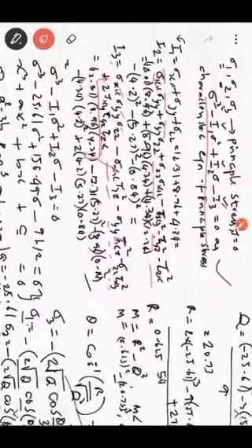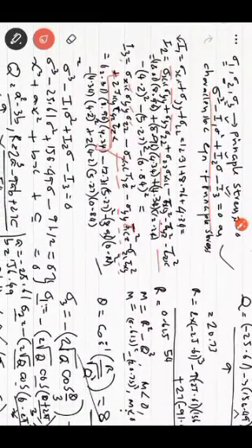And you have to add 2 times tau xy tau yz tau zx. These are all formulas you must memorize. Once I have found this, I will get this 3-dimensional equation. This polynomial is of third degree, so we will have 3 roots, sigma 1, sigma 2 and sigma 3.